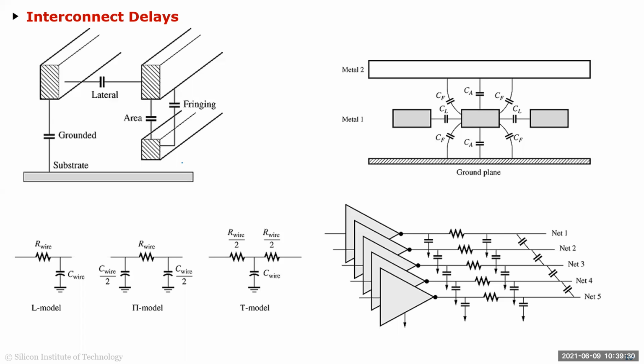Okay. And we talked about the interconnect, and something was talked in detail about the different models we use. So every wire is basically RC, and you have the lateral caps and then the bottom plate caps, which is the area plus the fringe caps, especially with the shorter nodes, because they're so close by that the fringe field is much more important right now.